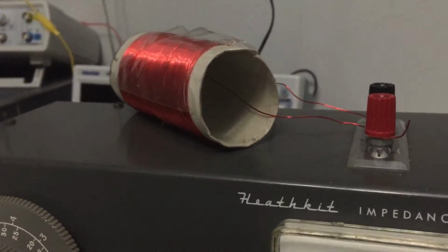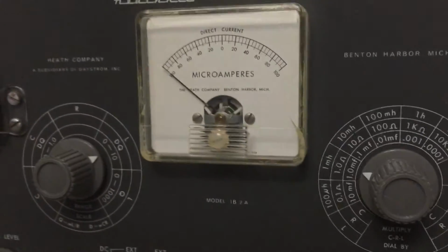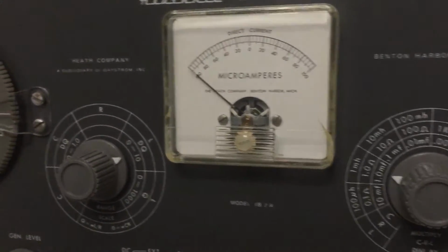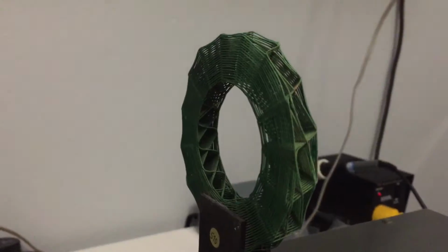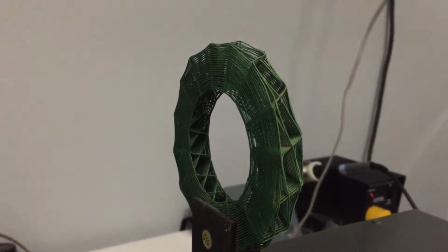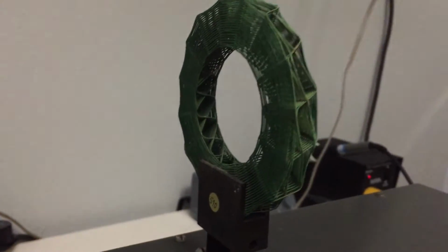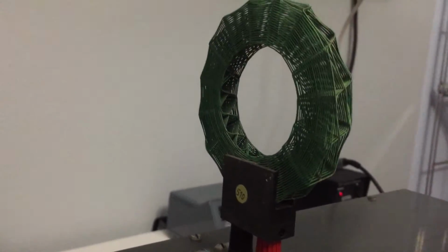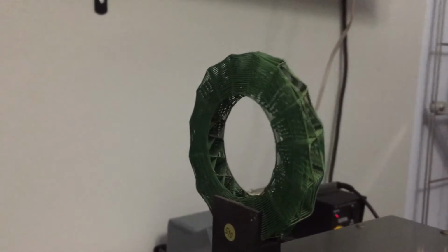As you see here demonstrated, we were able to read with great precision the amount of henries of a particular coil using the IB-2A, using this function as displayed. I'm measuring the inductance of this coil that I have from a very nice crystal set that I got in Switzerland. This coil is wound for 510 kilohertz. I happen to know this.